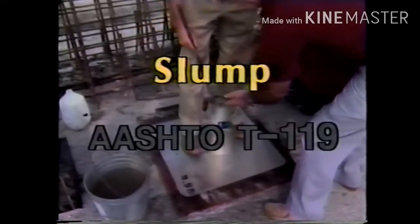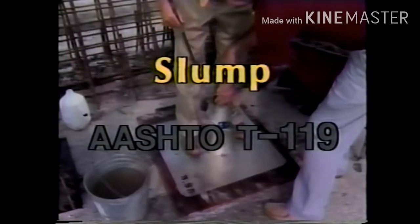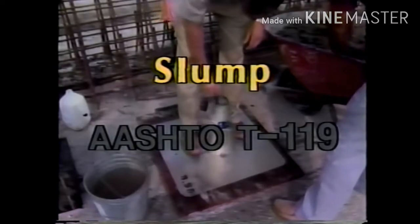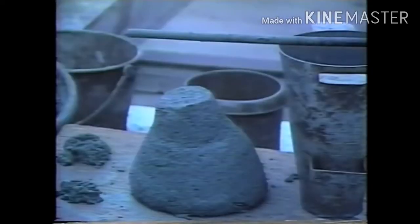Next on the list is the slump test, AASHTO T119. This is by far the oldest and most widely used test to measure the uniformity and consistency of concrete. Variations in slump generally indicate that changes have occurred in the properties or proportions of cement, aggregates, water, or admixtures.